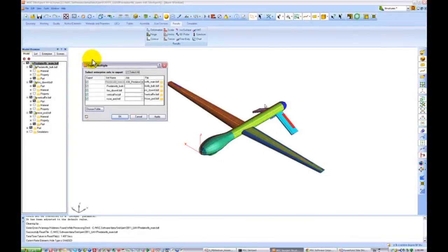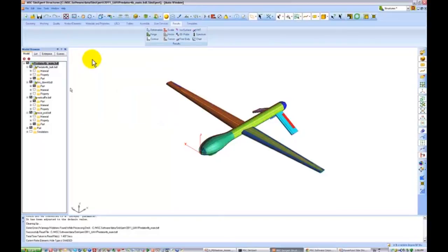So if you work on a component and you need to resend the center fuselage to a team that is working on it at detail level, you can actually re-export this and maintain the fact that it's sitting in a different file set. Now, once you have this data structure maintained, these are all objects that can be pointed to and managed using the Enterprise Model Browser.